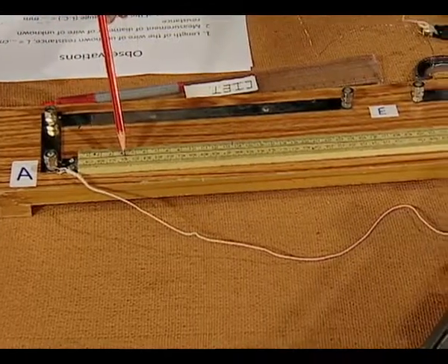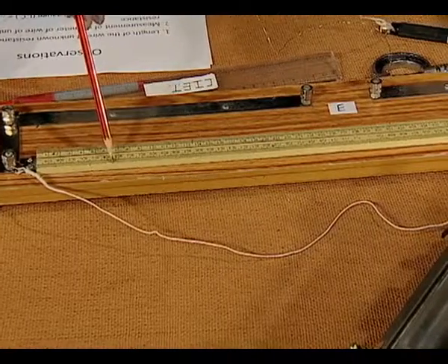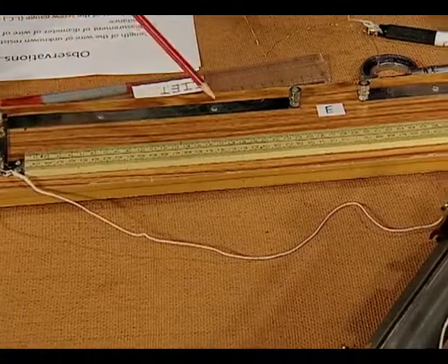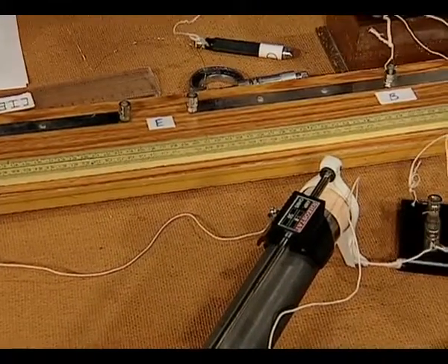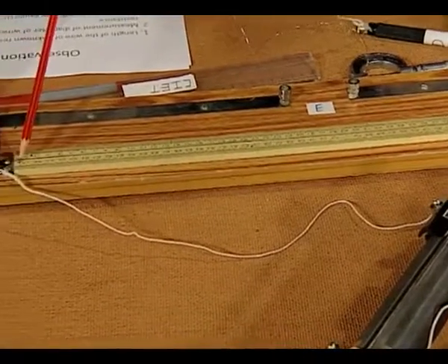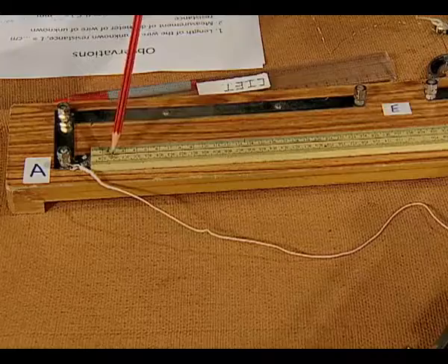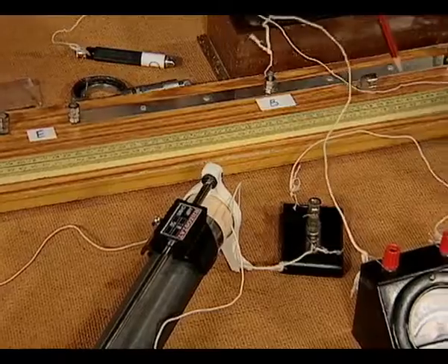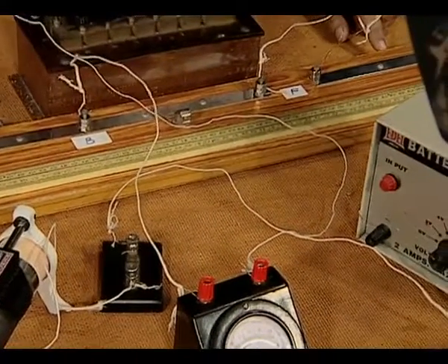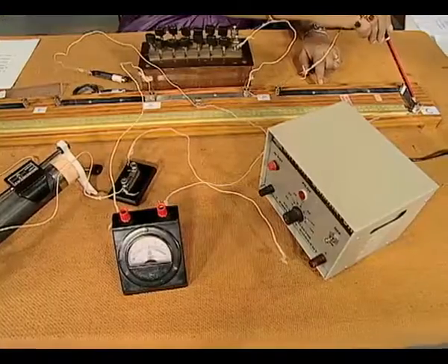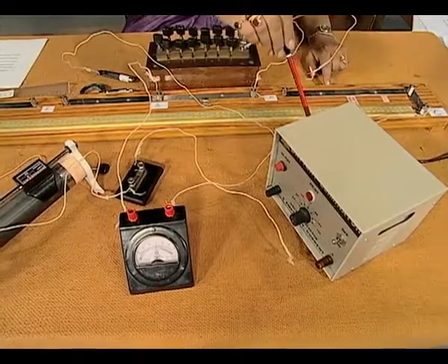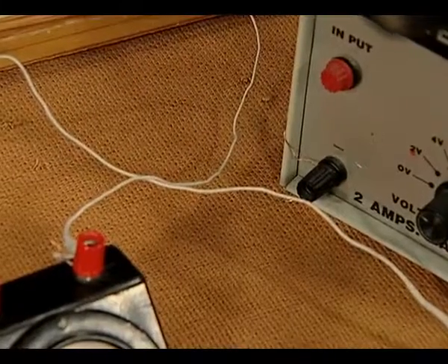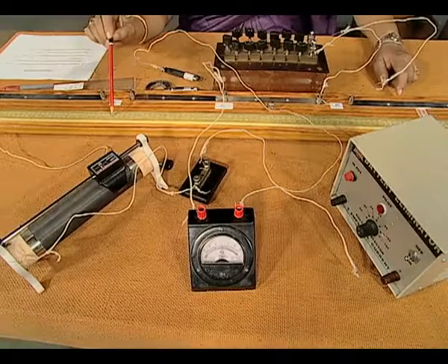The meter bridge wire is this. Attached to it is a meter scale. As you can see, it starts from 0 here and ends at the 100 mark on the other side, and there is a 100 mark here, which means the 0 for this side of the scale is on the other side of the wire. This is the 1 meter length of wire that you can see, and we go on to its other end, which is the point C. From C, the wire connects to the negative of the battery eliminator. So, this is our basic circuit for the bridge wire.